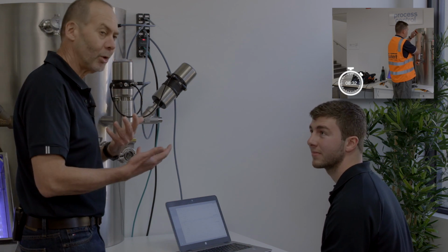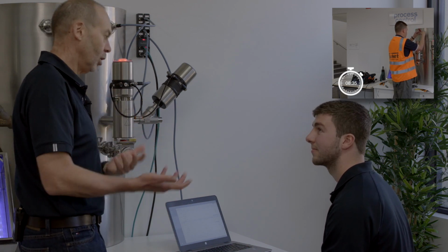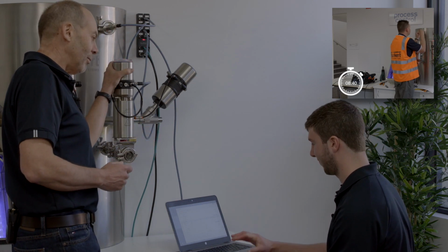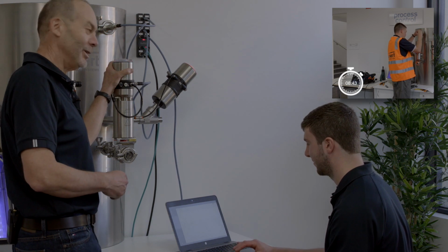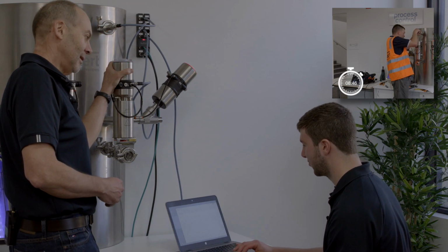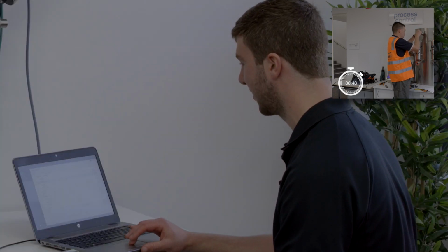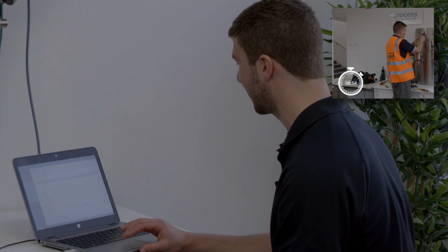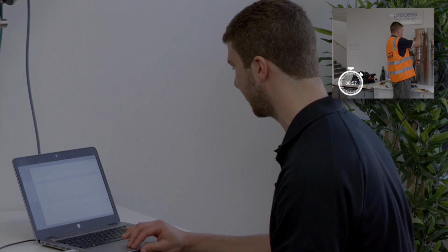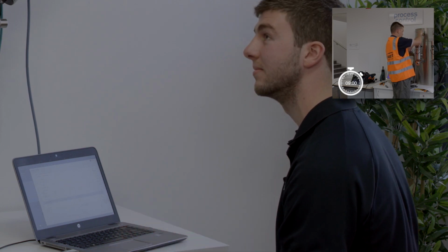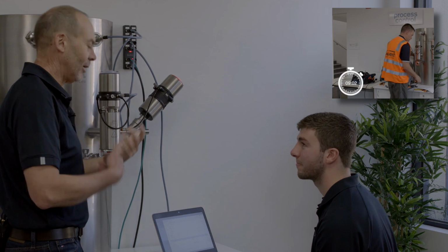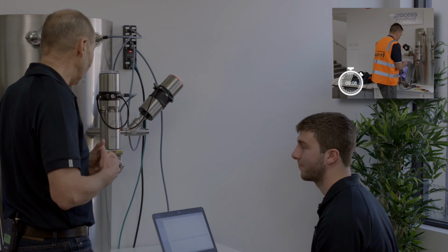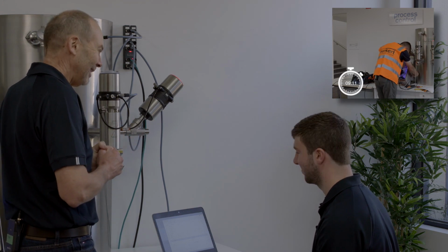So we can actually set points on that so they can tell you when a valve needs servicing or replacement, etc. That's right. Can you tell me the ID number of this control top and when it was manufactured? All right, so jumping into this device, we can actually see all of the maintenance data for it. And the ID number for this one is 307376, and it was manufactured on the 11th of June 2019. There you go. So this sort of data is just standard when you have digital connectivity. Of course, you get none of that when you have an alternate wired system. Well, you're all clear then. Awesome. Let's see how Nelson's going.